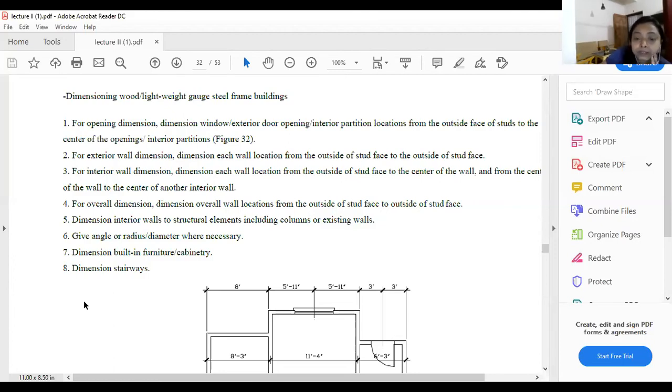So there is a process of making all these plans, because it has to be overlaid right from the base, right from the ground floor plan. Everything should be in mirror, or in similar line and length to the ground floor. If you have some extensions, that will be presented in a different format. So for that, you should always use this kind of architectural language.